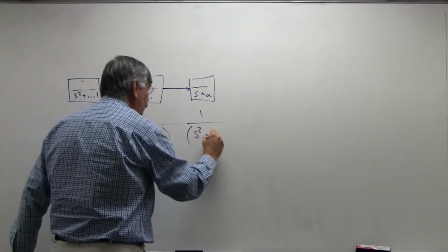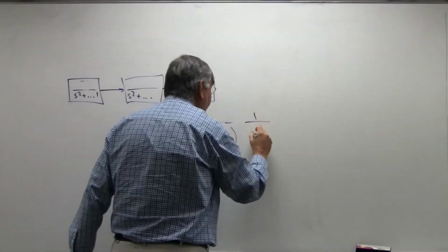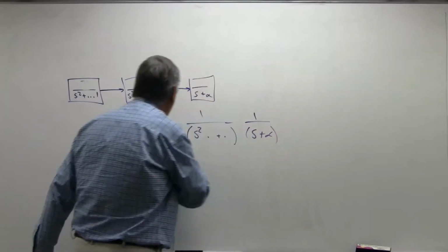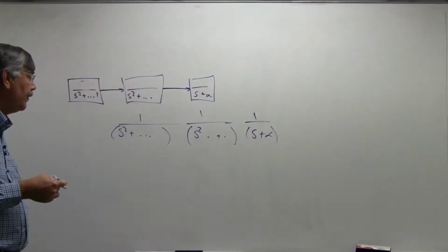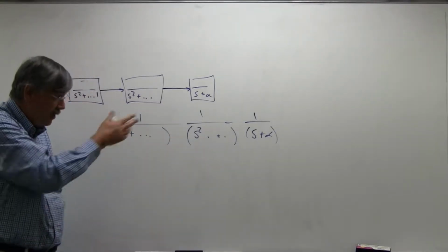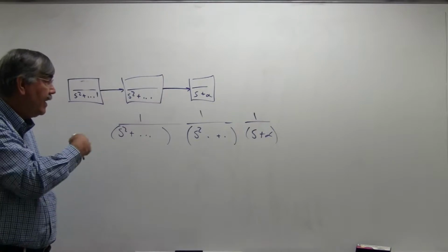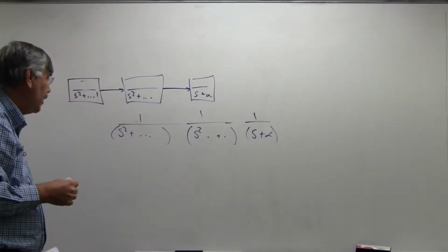And of course, when you multiply all this stuff out, in the example I've shown here, this would be a fifth order circuit because it's got s to the fifth power as the leading coefficient. So this would have 5 poles, 2 pairs of which are complex conjugate and 1 real pole. If we had an even number of poles, then they would usually all be complex conjugate. Now,